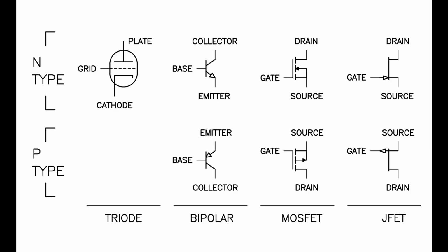One of the things I really like to do with audio amplifier design is play with the gain devices. Some audiophiles obsess about wire or capacitors or even resistors, but I find that performance differences between gain devices, tubes, bipolars, and FETs, totally dominates the experience. Pictured here is a simple listing of the four basic types, each having P or N-type counterparts, excepting the tube, where its polar inversion exists in some other universe.